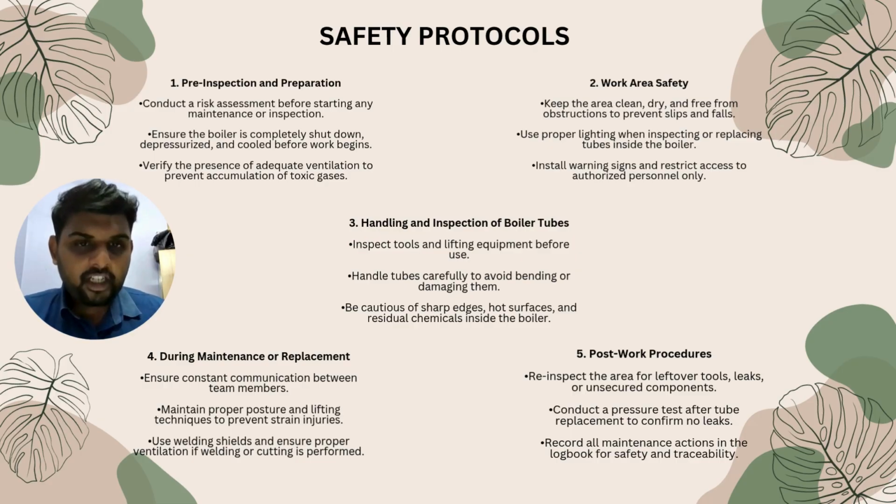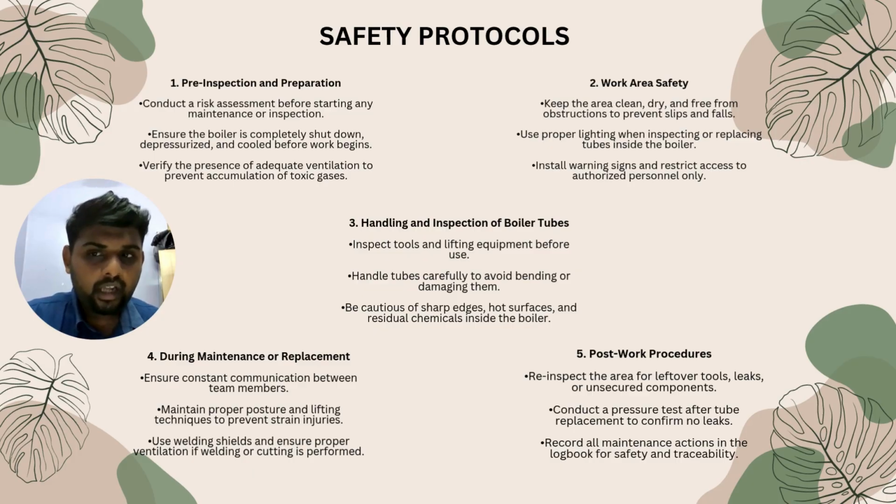Then we need to ensure adequate ventilation for welding or cutting. Then, always we need to monitor oxygen and gas levels in confined spaces. Finally, we never work alone, and we need to have a standby person outside the boiler who will tell us whenever an emergency happens.